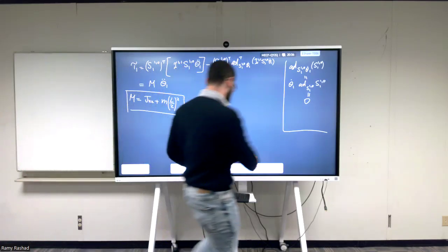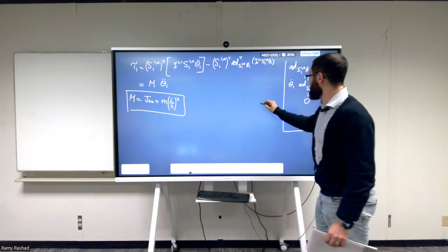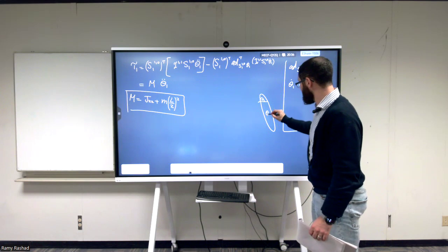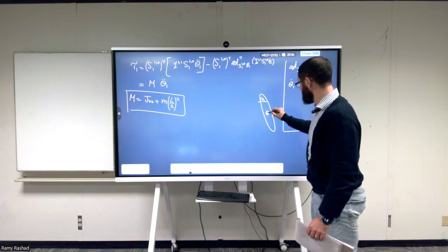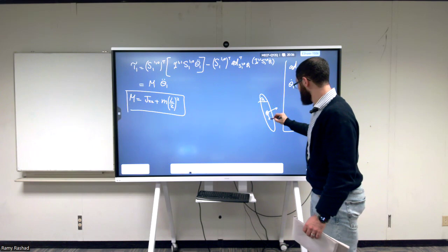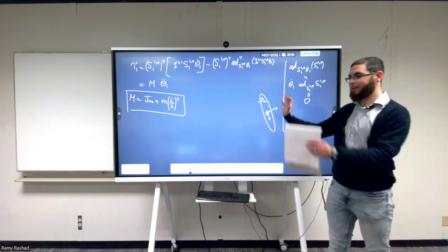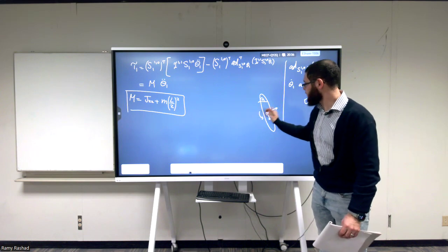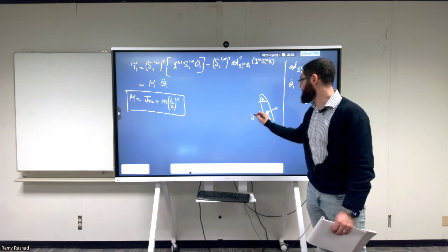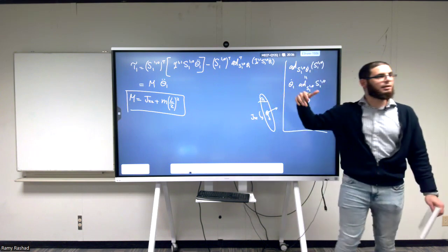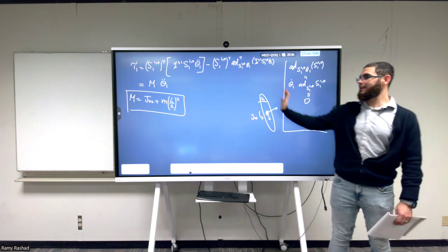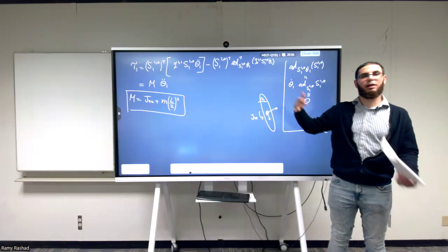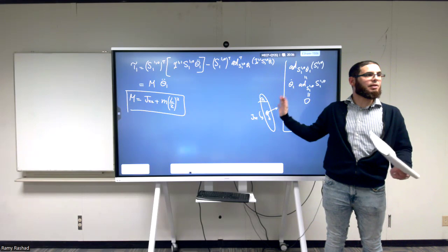To go back to the picture, our picture was something like this. We had here a lumped mass. So this was the center of mass. But this part also has an inertia, right? Inertia around this frame. So if I rotate around this frame, I have some inertia, which is the JZZ, the rotation around the Z axis. It's the only thing that affects the motion here, because everything else is constrained. I'm not allowed to move in any other direction except this one.